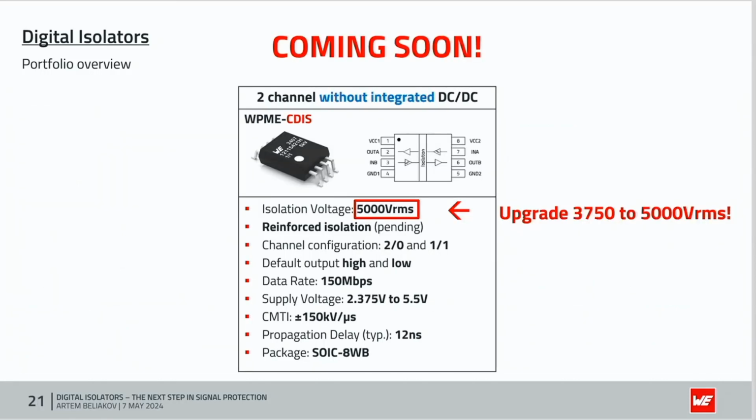Also, we are going to extend our portfolio soon. I hope it happens this month. We are going to have two-channel digital isolators without integrated DC-DC converter, but in a wider package, SOIC 8 widebody. It helps us to increase isolation voltage up to 5000 volts.